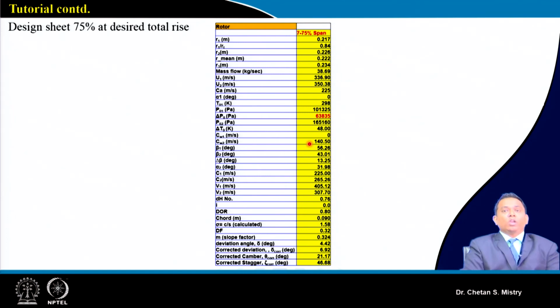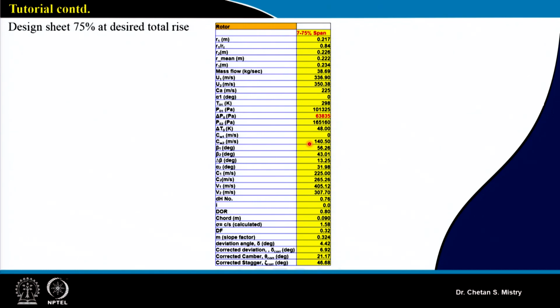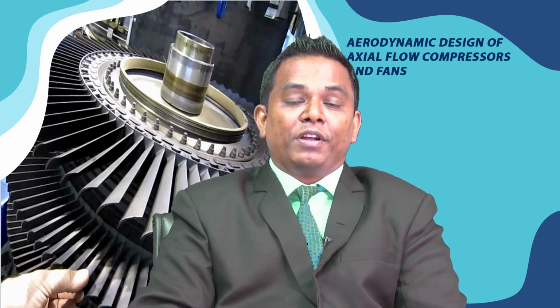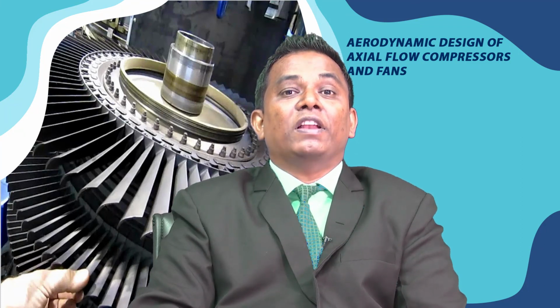Okay. So, here we are stopping with this fundamental understanding of the mid station calculation. We will proceed further with the calculation of parameters at the hub and at the tip section, and based on that we will try to finalize the design for this constant tip diameter configuration.